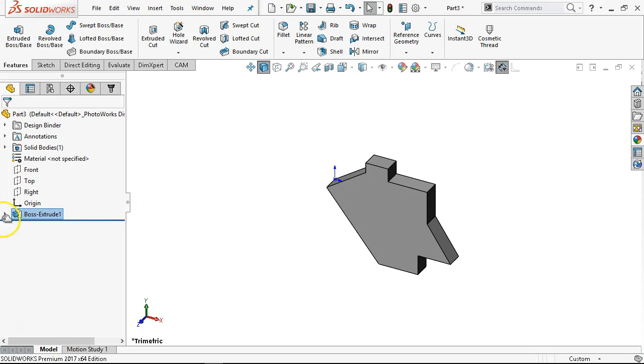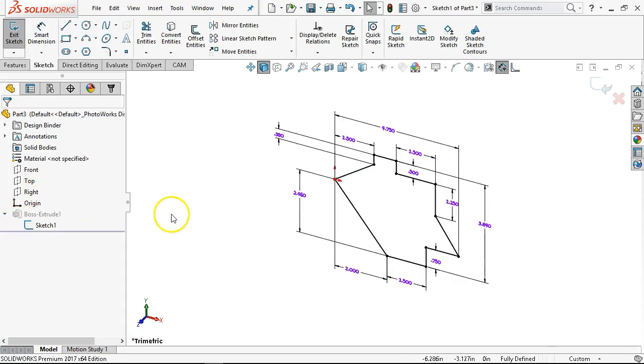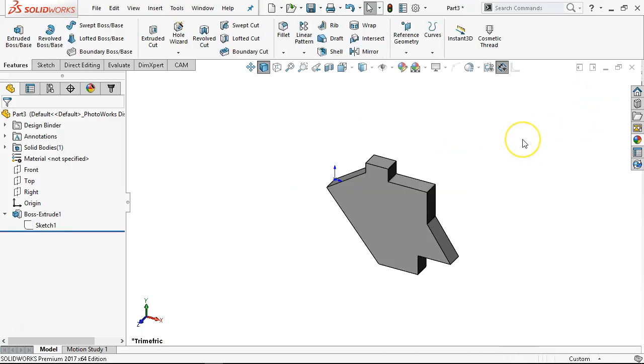So I haven't mentioned that SolidWorks will let you, I guess it's been for a few versions, save inside of the sketch. Previously you had to exit the sketch before it would let you save. I would still say that that is probably not a best practice. If you need to shut down, going ahead and creating the boss or getting out of the sketch is probably a better practice.